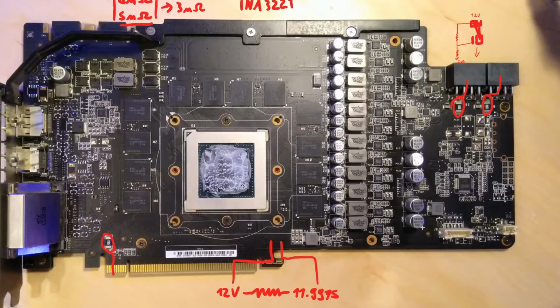And for most people this is perfectly fine. If you just want some extra power limit for some light overclocking, or just you want a higher power limit for dailying, because again on 20 series cards the VRM can take it. Like, these VRMs are extremely powerful. Like, my 2080 Ti has a 16 phase of 70 amp smart power stages. Though they're not gonna be running at 70 amps all the time, because then it would be very inefficient, 16 of those still are a lot of current that you can push through the card before you get problems.